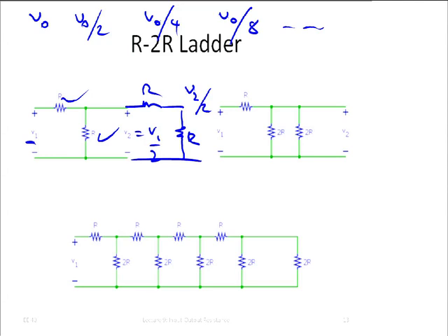No, actually, here is the voltage V2, and then we simply have a voltage divider, and so the voltage across this resistor is V2 divided by 2. That will always be true, regardless of the current that's flowing. But there is something that is now messed up. What is it? Yeah, exactly. This one here is no longer V1 over 2. Why not? Because there is current flowing here.